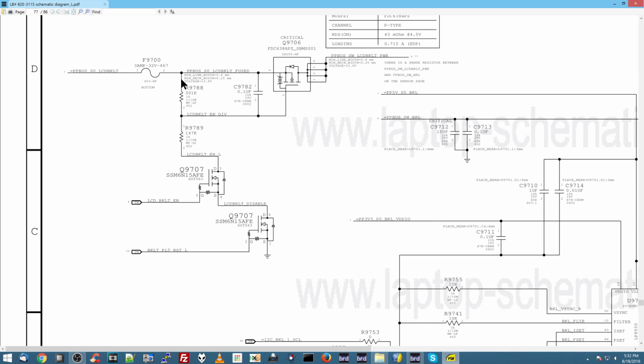I'm sorry about that. So the idea here is that if we have 3 volts here and 3 volts here, that means that these transistors are being told to open. But the voltage over here is not being dropped. The voltage over here not being dropped could be because of a couple of things. Either this is not having a path to ground, or there is a path to ground, but the capacitor shorted, or the transistor shorted over here, so that even though there's a path to ground, this 147 kilo ohm path to ground over here, it's not dropping anything because the 12 volt rail is shorted to this.